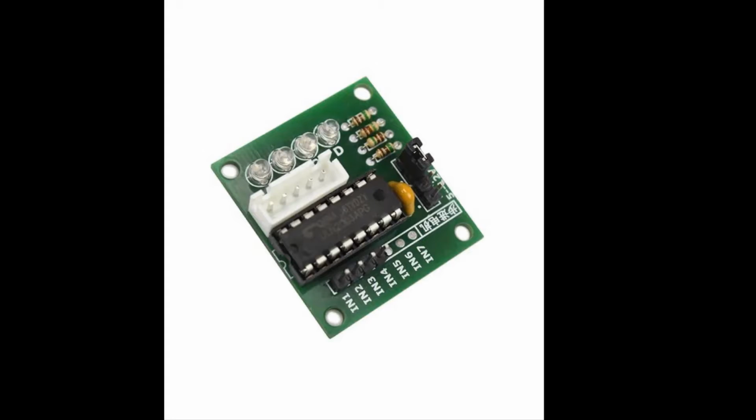The current required to drive coils by applying a sequence of control signals is almost 200 milliampere. GPIO pins of Tiva Launchpad cannot provide current of that magnitude. Therefore, we need a ULN2003 driver which translates the low current output of Tiva GPIO pins into higher current that meets the requirement of the stepper motor control signal.